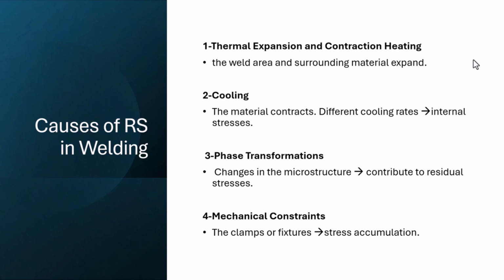So the second one is cooling. The material contracts during the cooling, and the different cooling rates of different zones of the material, as shown before, cause internal stresses and residual stresses. The next one is phase transformation. During the welding, the material phases change, and we have different zones of welding which contribute to residual stresses.